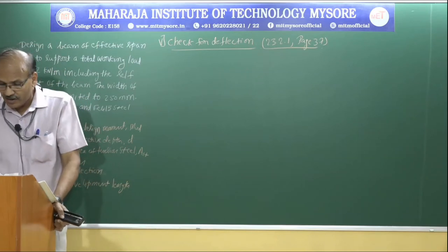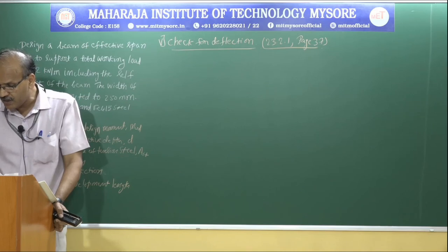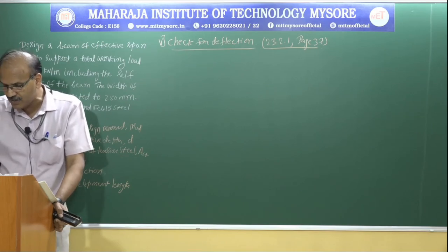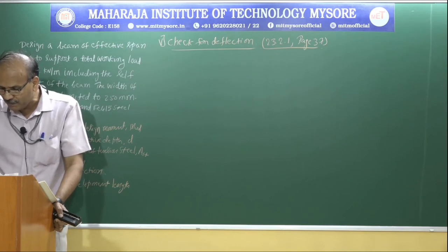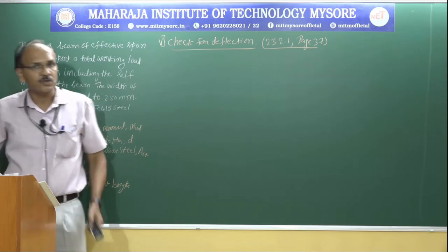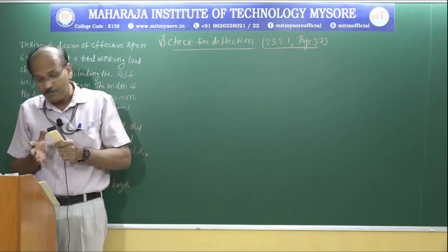Next, we will go to the next point C. It says depending on the area and the stress of steel for tension reinforcement, the values in A or B shall be modified by multiplying with the modification factor obtained as per figure 4. So this modification factor we are going to apply for tension steel.